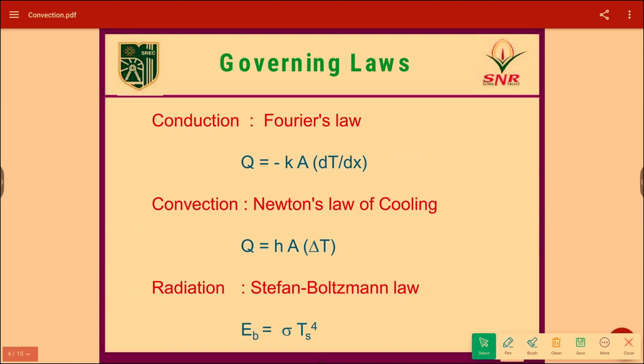Now we can see the governing laws of the three modes of heat transfer. The conduction mode of heat transfer is governed by Fourier's law, which is given by Q = -kA dT/dx, where k stands for thermal conductivity.